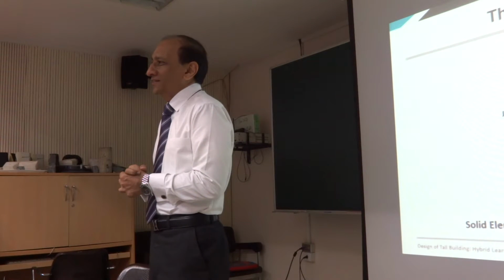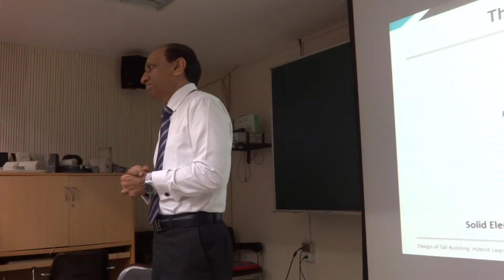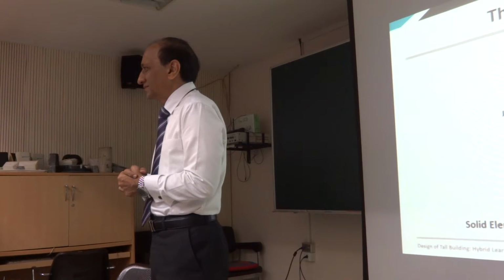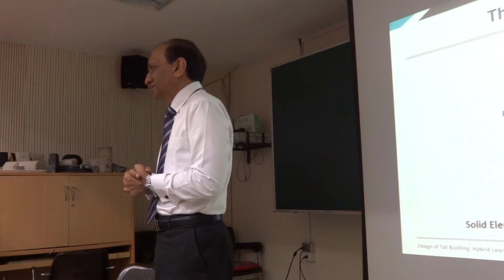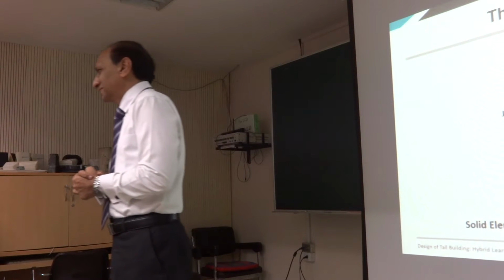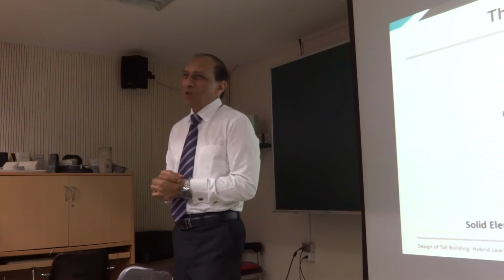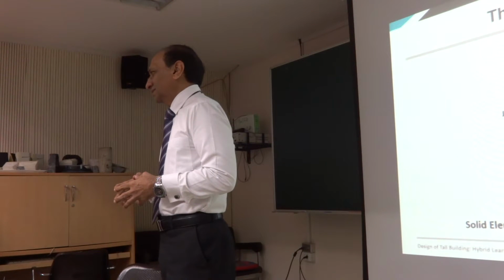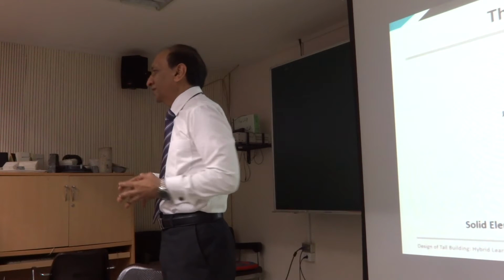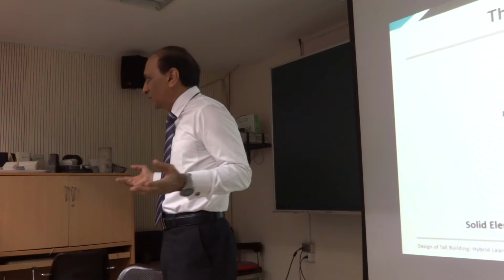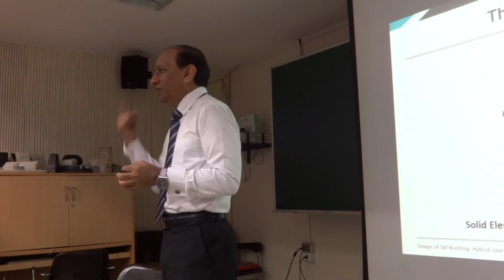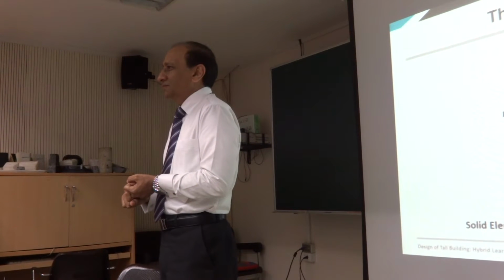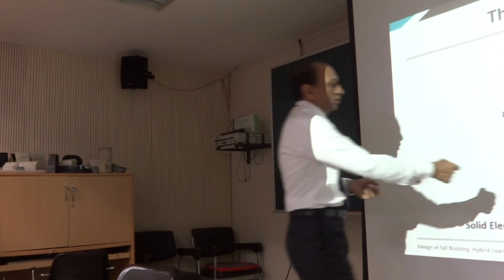How many material properties are needed? What are those 3? No shear modulus. Shear modulus does not exist. Only 3 elastic modulus, in each direction can be different now. That's it. You can't have shear modulus because you don't have corresponding shear stiffness. There is no stiffness here anymore. Only axial. Nothing. 3 degrees of freedom. Only axial. No bending, no torsion, no warping, no nothing. Only 3 degrees of freedom for each node to move this way.